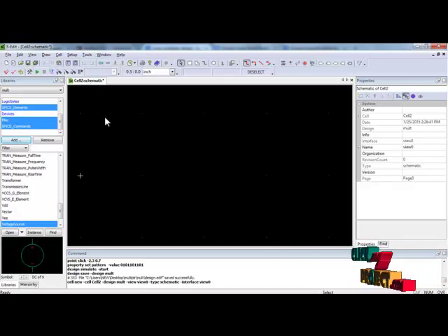Each cell should contain a different CMOS design. The next process is to set up the simulation. This icon, when pressed, leads you to the simulation setup. In the setup, you have to set the maximum time duration for the design, in nanoseconds.